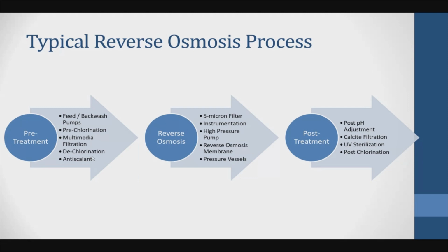If we pass the water to the membranes without getting rid of the chlorine, that's going to cause major damage to the membrane. Most of the membranes that we see in the market right now should not handle more than 1,000 hours based on 1 ppm of chlorine. That means if the water has more than 1 ppm for more than 1,000 hours, that's going to damage the membrane.